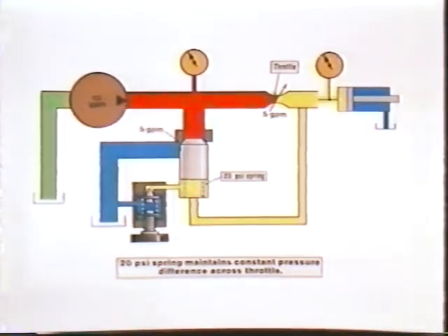If you recall, with a meter-in circuit or the meter-out circuit, using the plain needle valve, the excess oil went over the relief valve at the relief valve setting. With the bypass type, the pressure at the pump is just 20 psi over what the workload is. If the workload were 400 psi, the workload pressure back at the pump would be 420. So, comparing it to the meter-in or meter-out that we looked at just a little while back, it's saving energy for us.